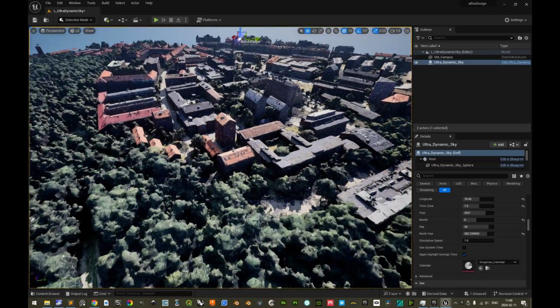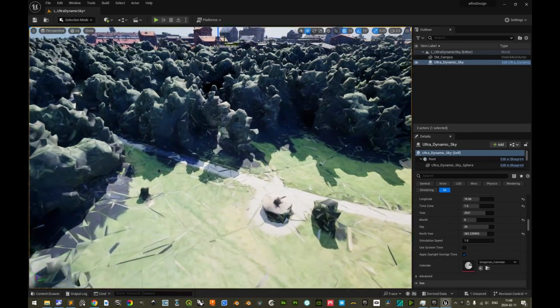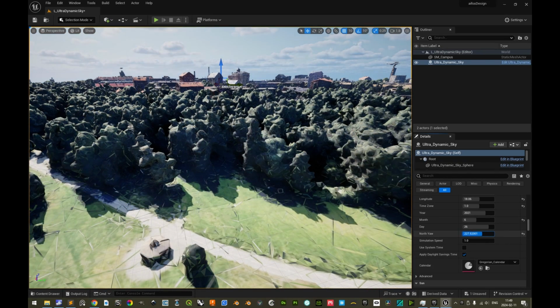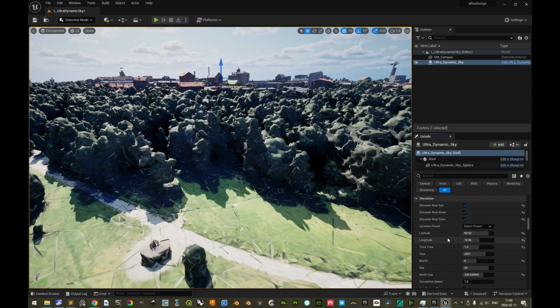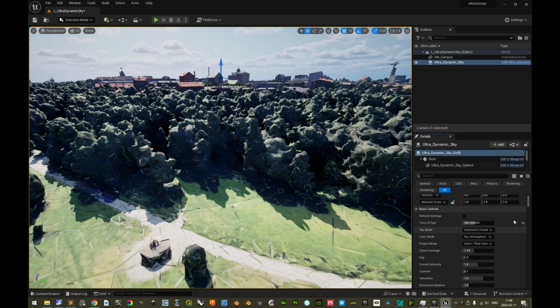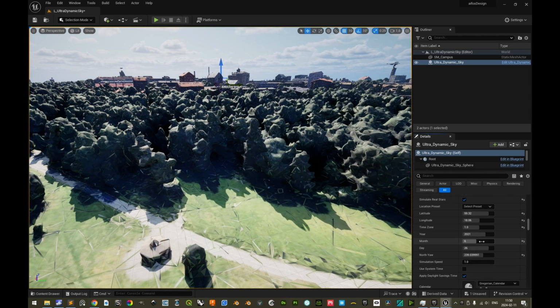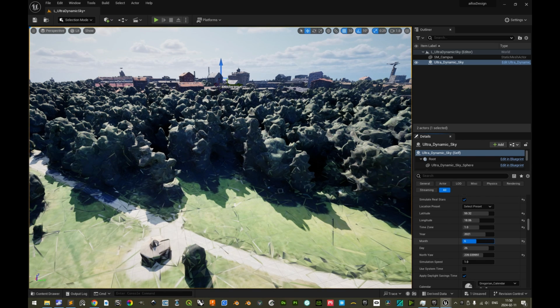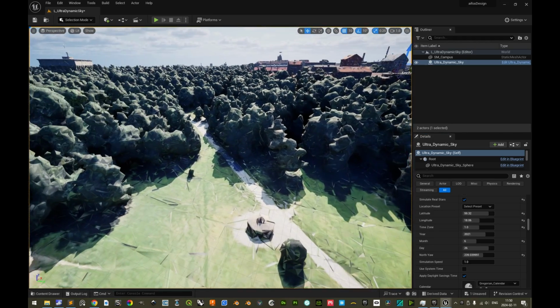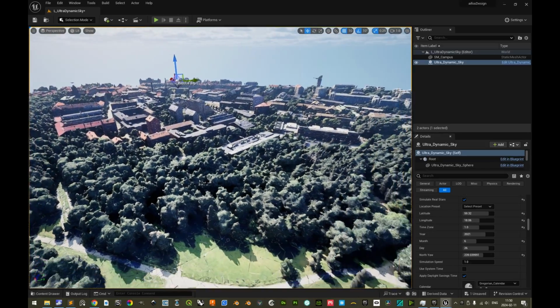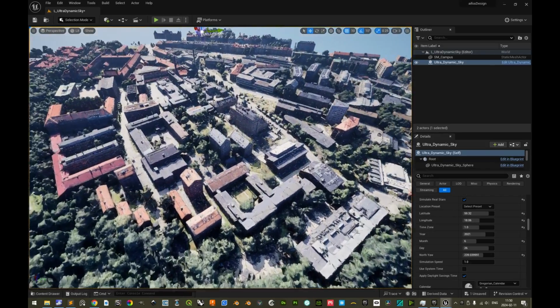Let's see, where are our shadows here? We can find that here, I think. Alright, so then we'll see here. Yeah, it should be somewhere like that, and then we might adjust the time. Or simply the month. So let's see here. We want to make it even higher, like that perhaps. Yeah, and this can of course be fine-tuned, and if the orientation of the imported mesh was according to the north, then it would be really easy. But let's do it like this.